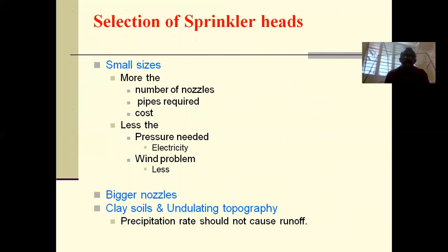On the other hand, if we use bigger nozzles, then the number of nozzles used will be very less, and the pipes used will also be less, and the total fixed cost will become very less. But operating cost will become more, because we have to throw the water to a larger distance, so pressure needed is more and electricity needed is also more. And wind problem will also be more, because the water jet will be in suspension for a longer time and for a longer distance.